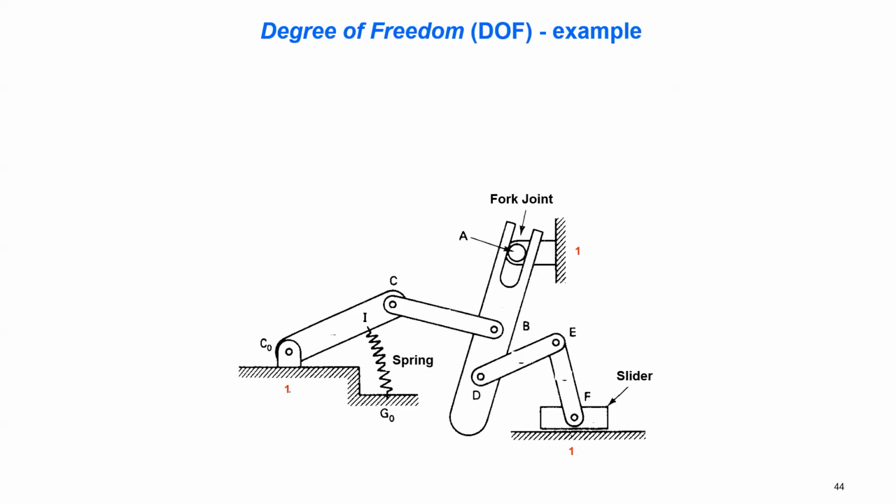So now you realize that the fixed part is link 1. Then we have this part as our link 2. This is our link 3. This is our link 4. This is our link 5. And this is our link 6. And this one is our link 7. That means that our L is equal to 7, right? Now we also need to find our J1 or P1, okay?